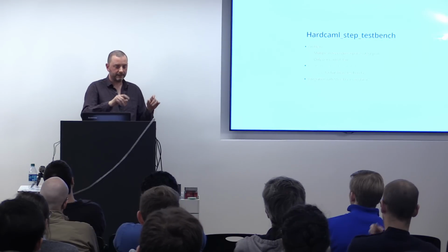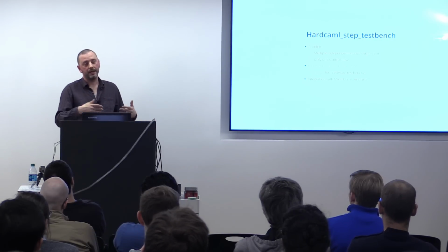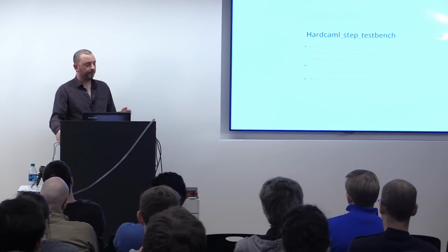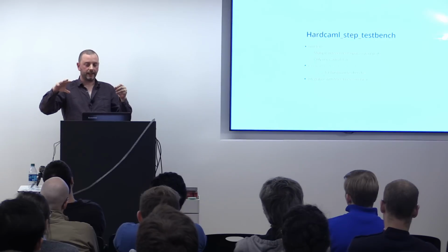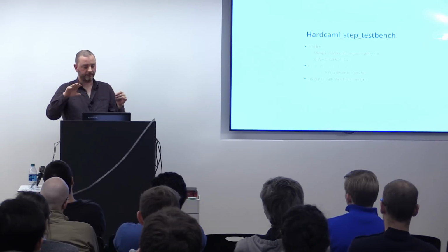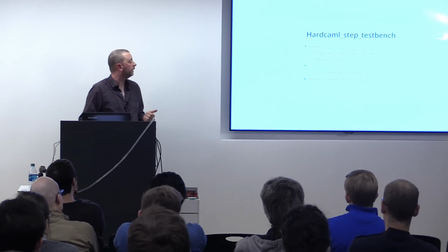It's not trying to simulate hardware. It's simulating the instruction set, so it's fast. So I don't know, maybe a few megahertz fast. But that can actually interact with a hardware design attached over the standard bus interfaces. In this case, it's like AXI bus for the Microblaze. That's really very, very powerful.